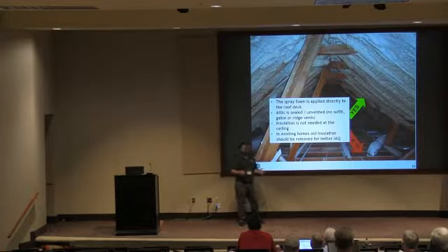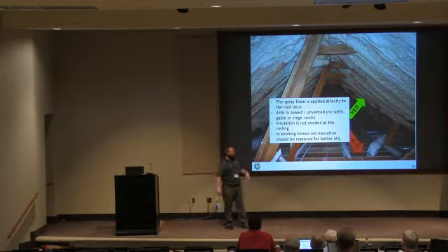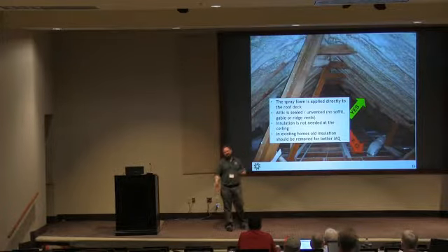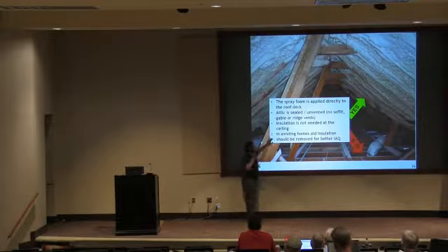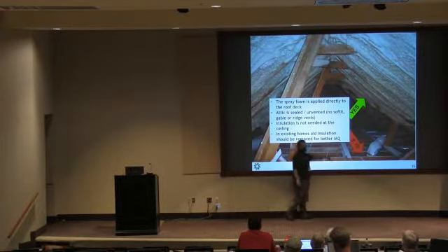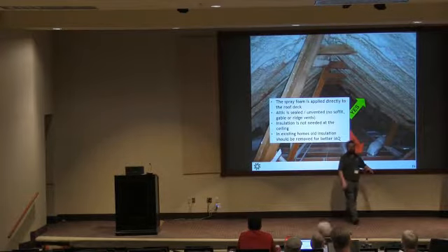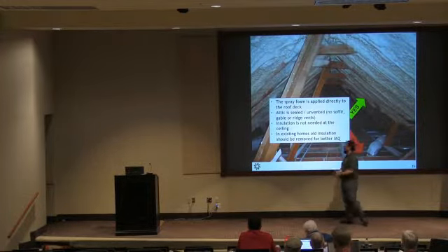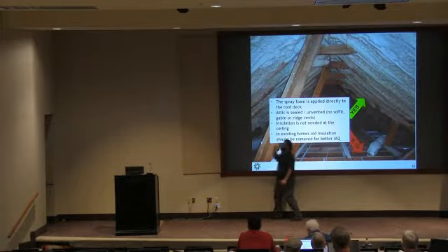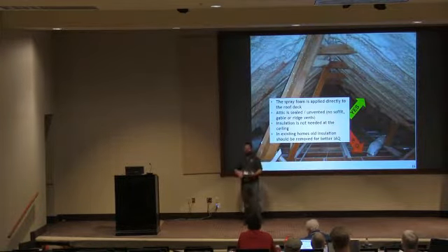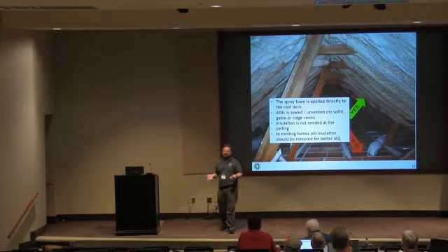These are great questions. I'm just looking at the number of slides I'm on at the time and going, y'all want to have dinner? But all that said, to answer your question, we do recommend when they do this as a retrofit, they remove that insulation that was already there. And the real reasons are, one, this is no longer your thermal boundary, right? You've moved your thermal boundary up to the roof line, so that insulation isn't your primary thermal boundary anymore.